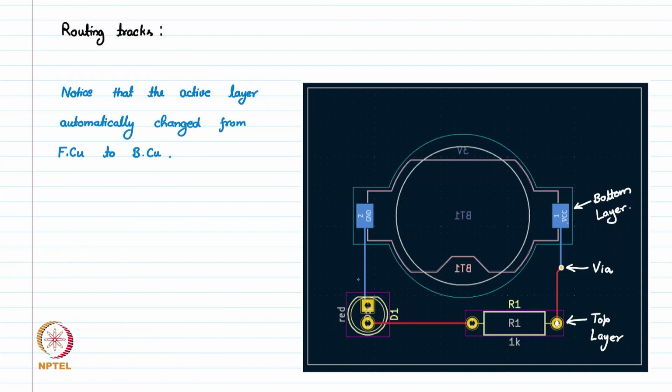However, there is one more step which is important to do in all PCB designs and very critical to do in high speed RF design: placing copper zones.